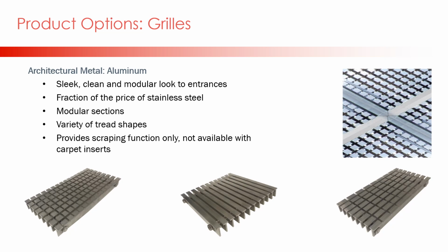One advantage of the waffle tread shape is the ability to manage cross traffic. Per the ADA requirements, the elongated openings shall be placed so that the long dimension is perpendicular to the dominant direction of travel. There are times where traffic is crossing in multiple directions as individuals enter the building. The waffle tread is a great option for cross-traffic applications.